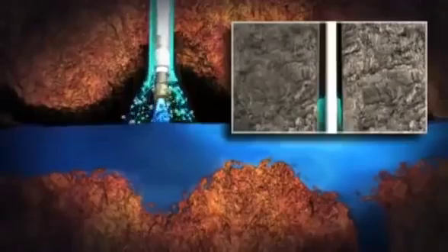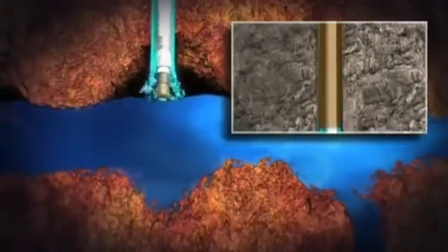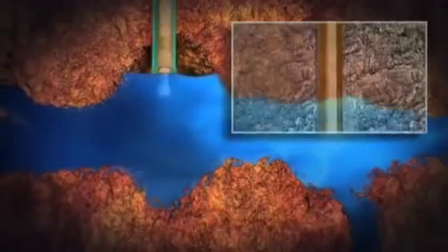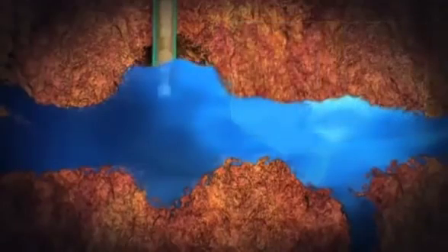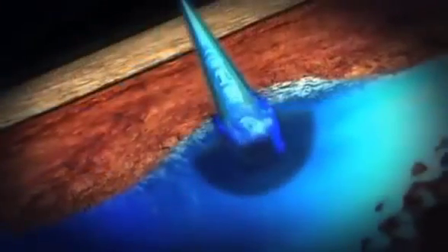With the casing shut in, the weight of the fluid cap is balanced with the formation pressure by managing the surface pressure. Casing pressure and gas migration is quickly and accurately managed through application of surface pressure and by adding or removing fluid from the top of the fluid cap.